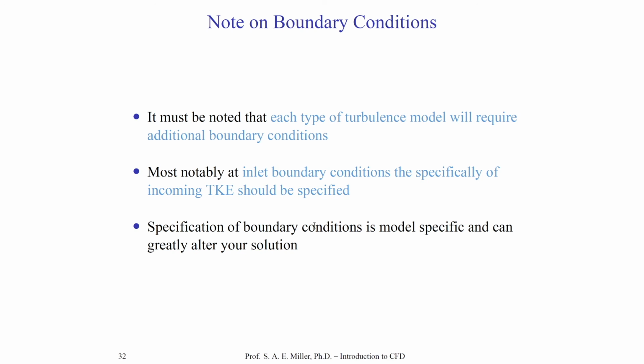Remember, if you do not know those values, you'll have to estimate them. And you might have to even use trial and error to select different turbulence quantities at boundaries to get the solution of physical characteristics you desire later on. So that can be a very difficult thing to do, and it can only be found with a little bit of experience and hopefully some insight into the flow through measurement or a flight test.